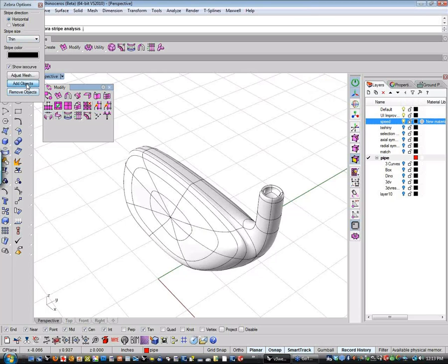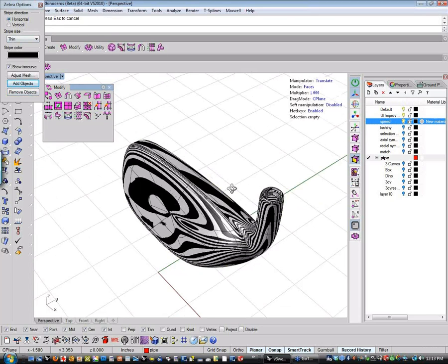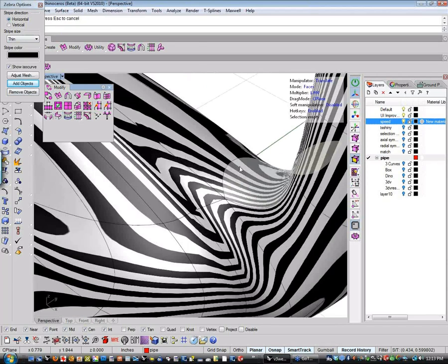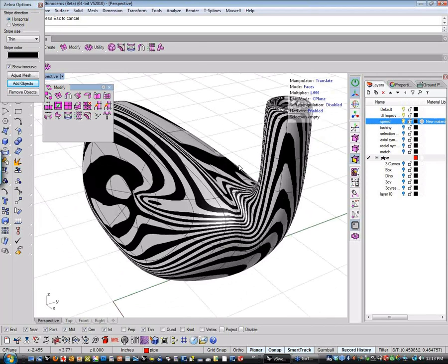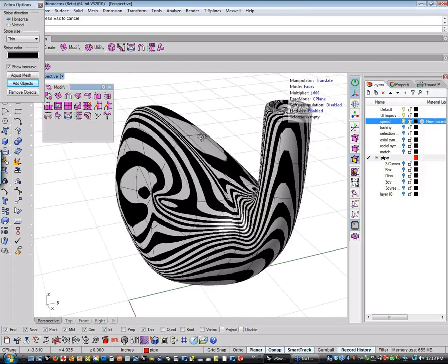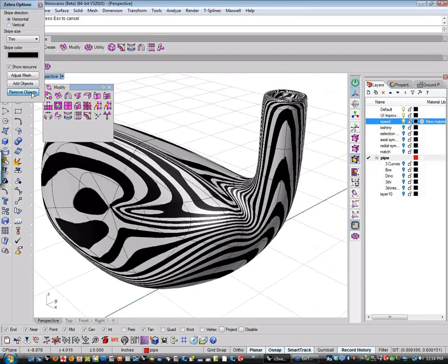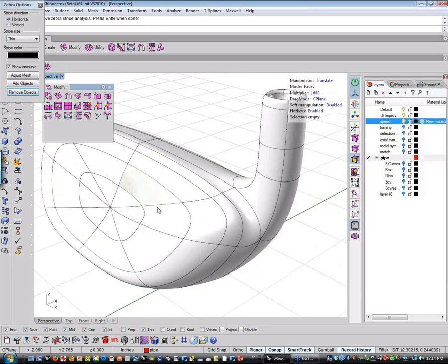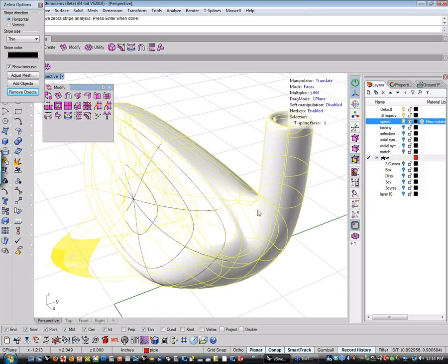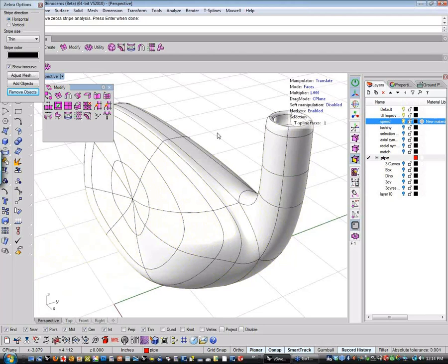If we zebra this, you're going to get full star smoothing. You're going to get the compatibility with all the Rhino commands, set points, and anything that you would access through the Rhino command window or any of the Rhino commands that you use on T-Spline stuff. This compatible mode allows you to access all of that stuff. But there is a little bit of a performance hit, and if you notice, there is some lag here. So this is pretty much where we were before.